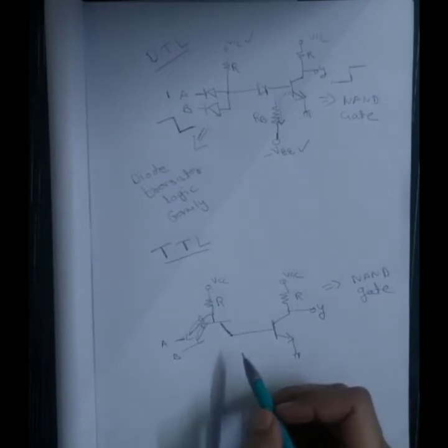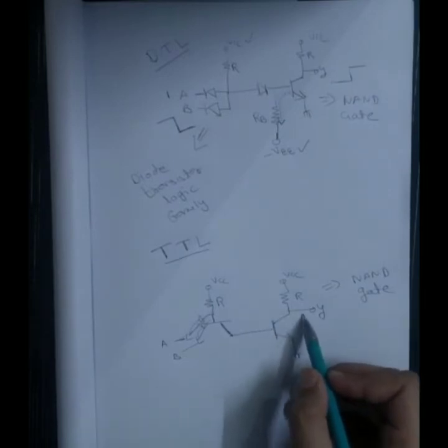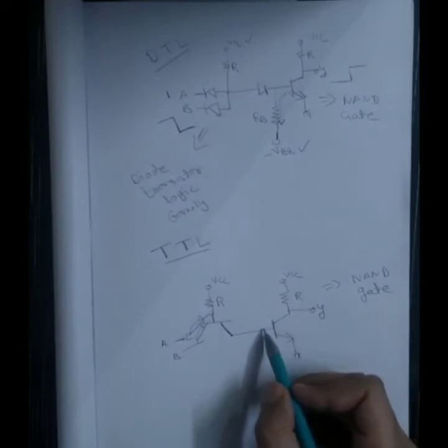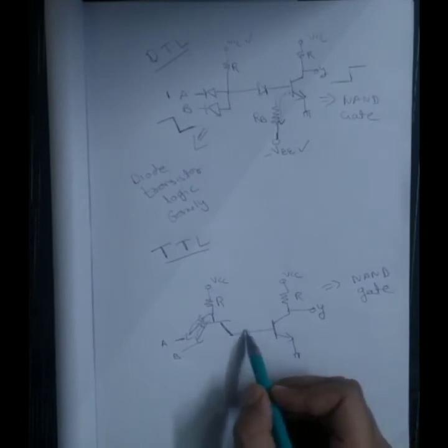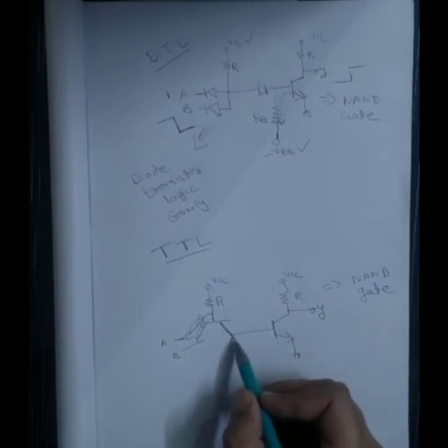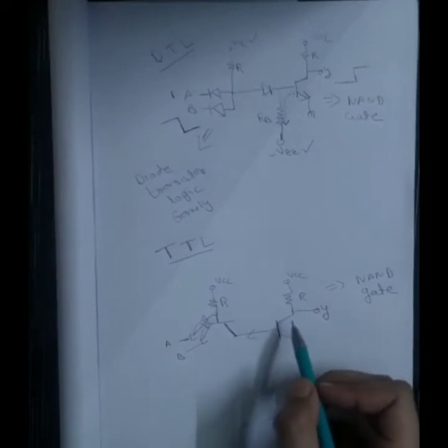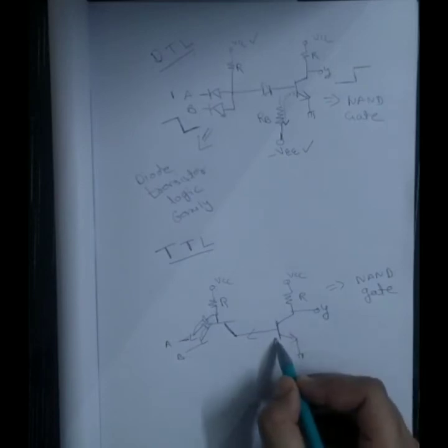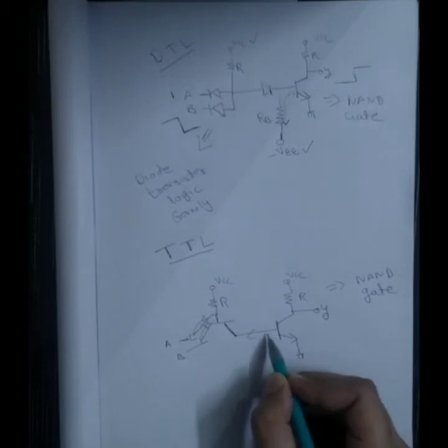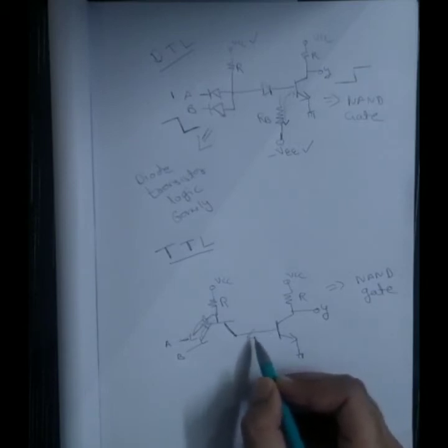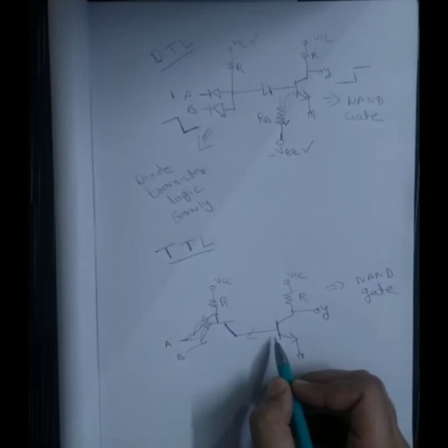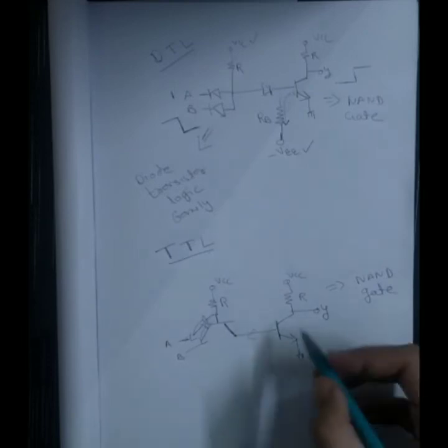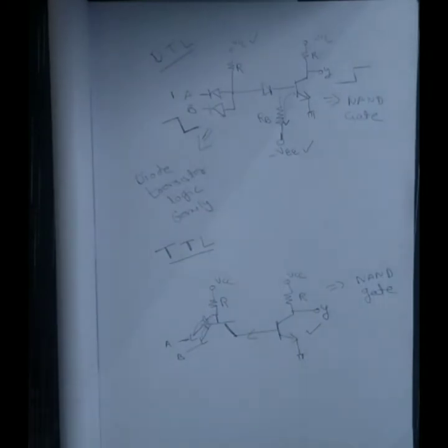Right, now see, when this transistor goes from saturation to cutoff, the current can flow here. Why? Because usually the collector current allows the current to flow in this direction, right? Collector current usually flow in this direction, right? So when this changes from saturation to cutoff, the charge which is built here will have a path to flow through this, because again this is the collector of a transistor, and through collector it allows the charge to go in this direction. So this is like far better circuit than this.